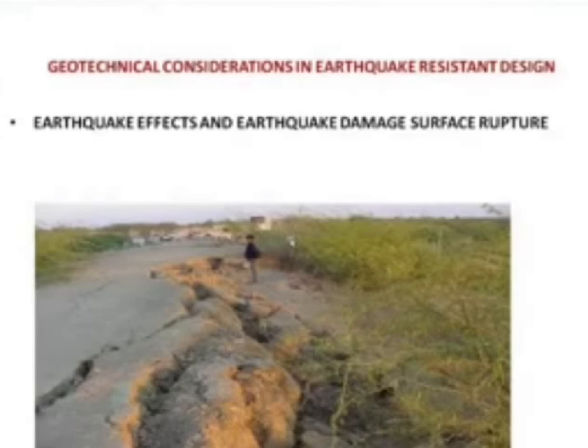You see, at some point of time, some place was in zone 2. But later on, depending on the nature of earthquake and the post-earthquake survey, they could appreciate that no, it is not in zone 2, it is like zone 3. So it should be upgraded to zone 3. And accordingly, the seismic map is changed in the IS 1893 code.